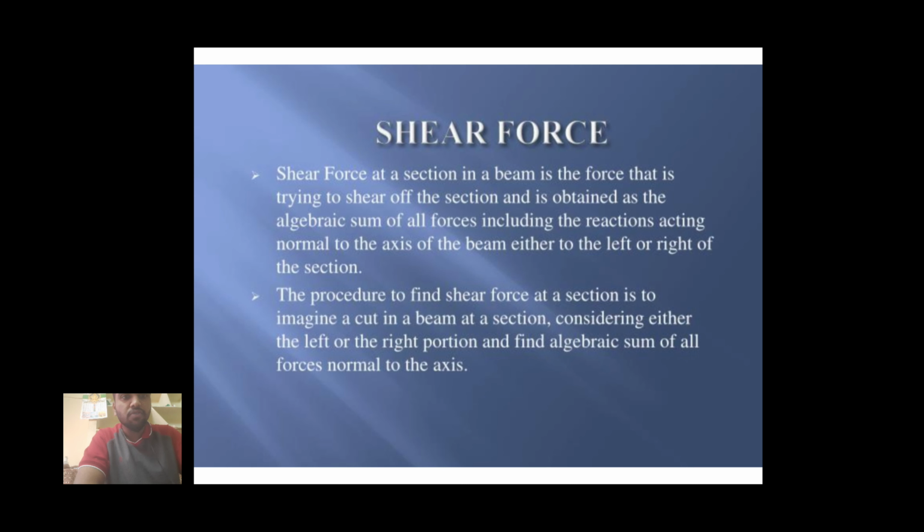Shear force. Shear force at a section in a beam is the force that is trying to shear off the section and is obtained as the algebraic sum of all forces, including the reactions, acting normal to the axis of the beam, either to the left or right of the section. The procedure to find shear force at a section is to imagine a cut in a beam at a section, considering either the left or right portion, and find the algebraic sum of all forces normal to the axis.